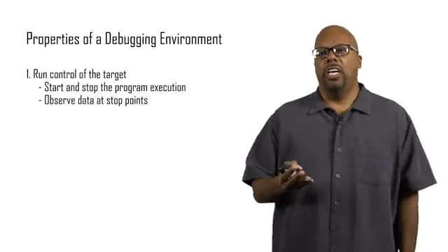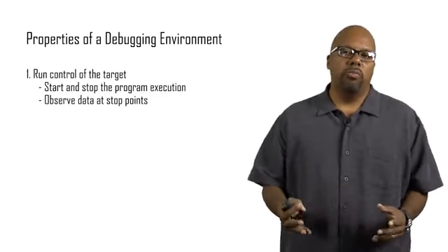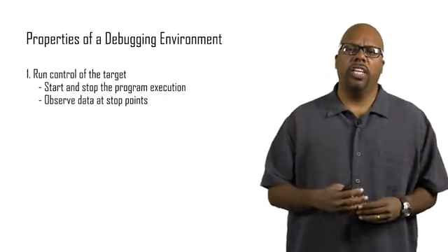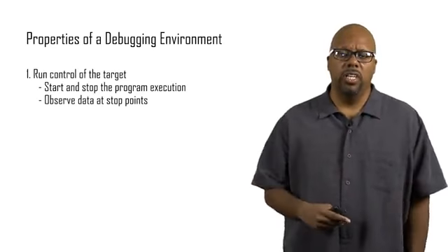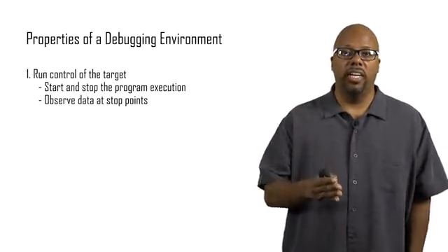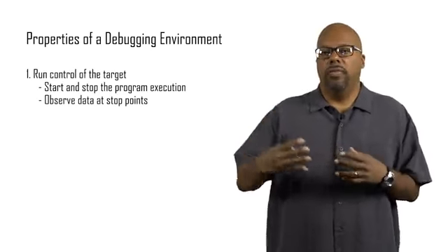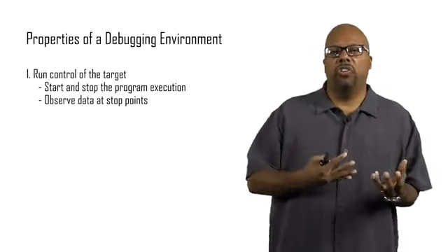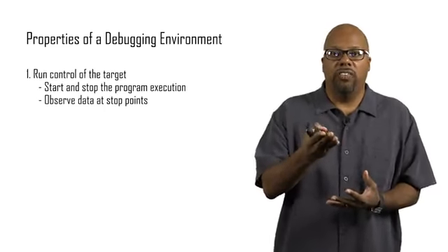Generally this is done using breakpoints. We won't be using breakpoints, but basically you look at your code and you see something's gone wrong and you have a suspicion: oh, I think the problem's somewhere around line 53. So you set a breakpoint at line 53 and you let the code run until line 53. Then it stops, and depending on your debugging environment's interface, you can look at the values of the registers, the memory, and the variables when you're at line 53.